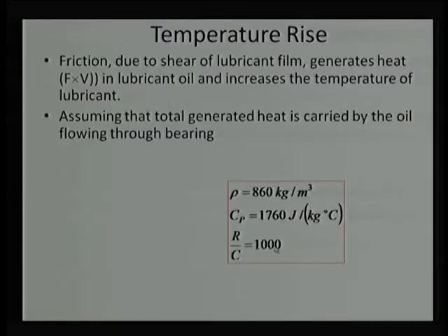So, to make sure that the Reynolds equation is applicable, we can use the assumption R by C is 1000. It can be lesser or more, it can be 900 or 1100, depending on the configuration, but just for the first initial exposure, or to get a feel of the temperature rise at the bearing interface or the tribopair interface, we can assume these data.